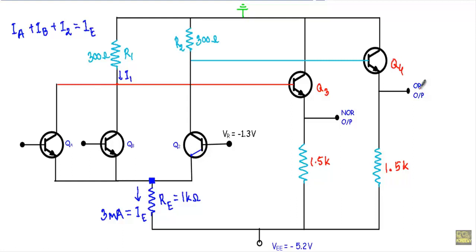In this circuit, you will see the transistors QA, QB and Q2 form a differential amplifier, and the operation of this logic circuit depends upon the operation of our differential amplifier. Here you see the emitter terminals of transistors Q2, QB and QA are coupled, or connected together. Therefore, this is known as emitter coupled logic.